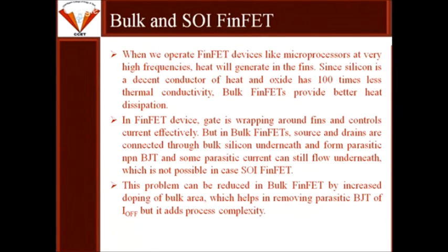So since silicon is a decent conductor of heat and oxide has 100 times less thermal conductivity, bulk FinFET provides better heat dissipation. I hope you agree with this, because in bulk FinFET, the fin is connected with the wafer, with the silicon bulk, while in the case of SOI, it is not connected. It is just over the oxide surface. So dissipation or distribution of heat will be better in the case of bulk FinFET.